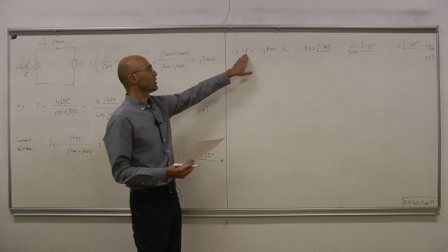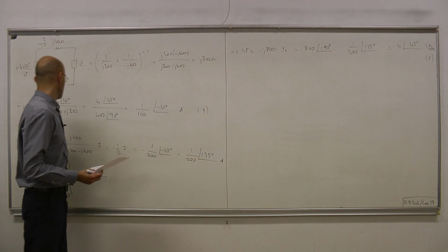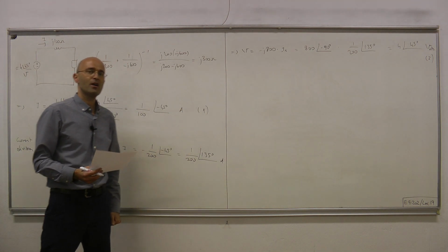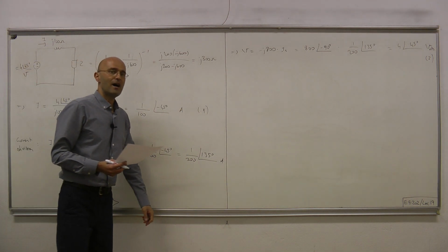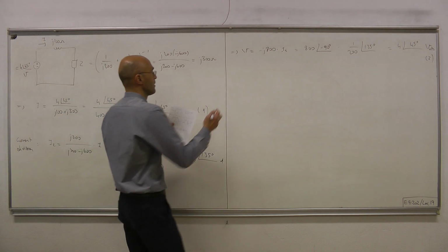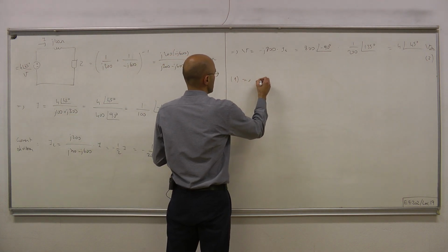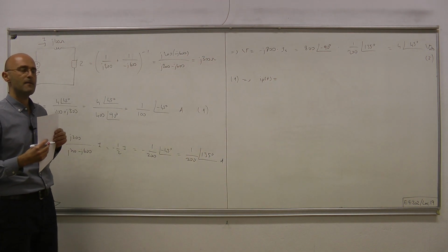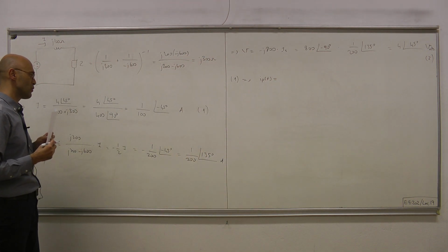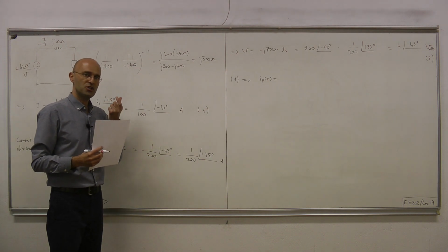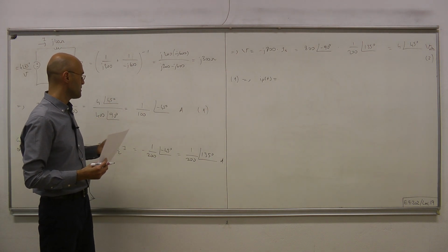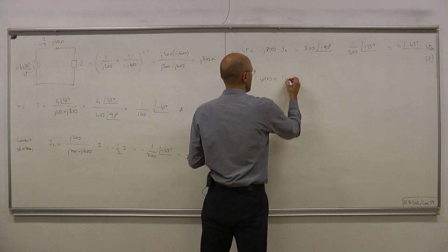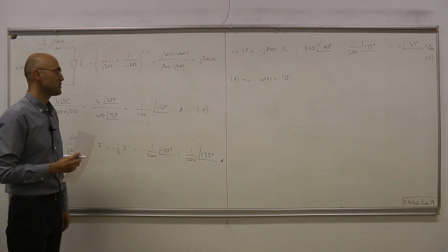We have the phasor of the capacitor voltage. We have the phasor of the source current I. All that remains is to transform those complex numbers to their time domain representations. Equation 1 immediately yields that the particular solution for the source current equals the sinusoidal signal whose magnitude is 1/100 amps, or 10 milliamps.